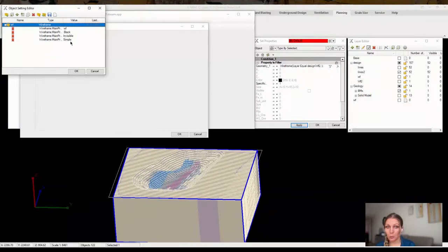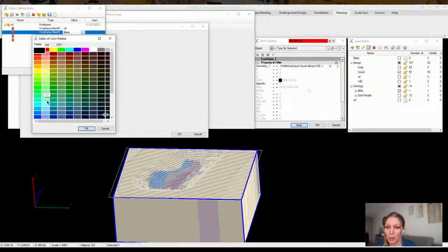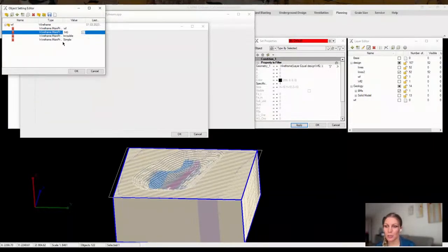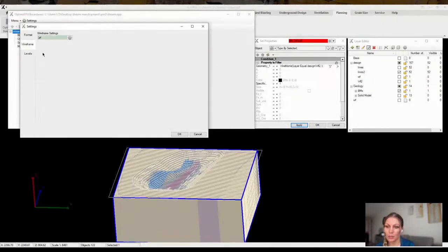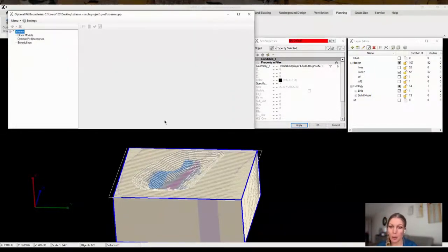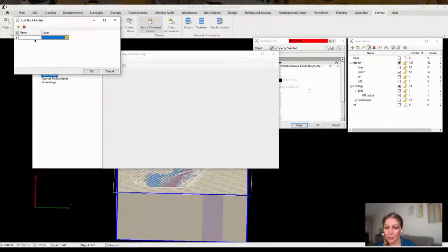And to make the information more readable, we'll configure the display of calculation results to present values in millions and with a single decimal point. Additionally, we'll set up the wireframe settings while leaving the horizon settings unchanged, as they won't be necessary for today's example.